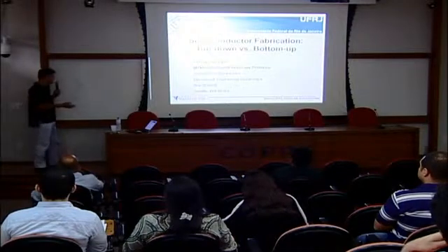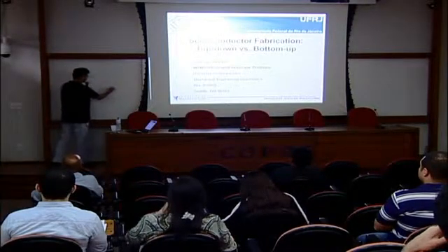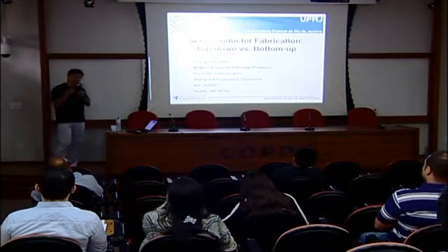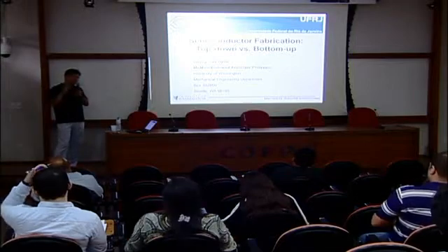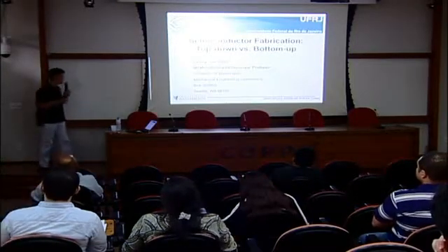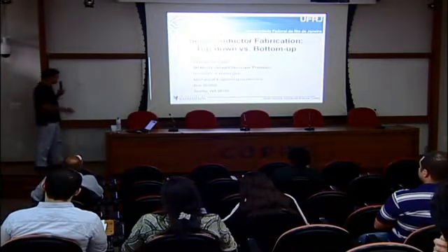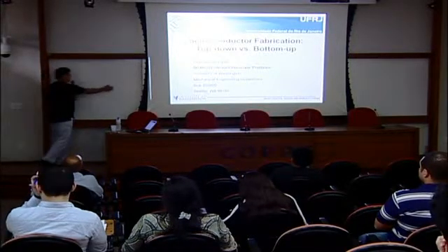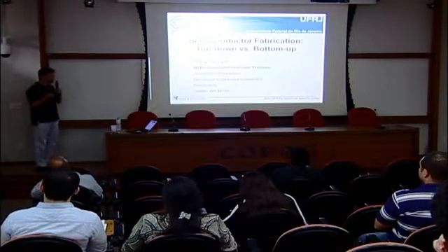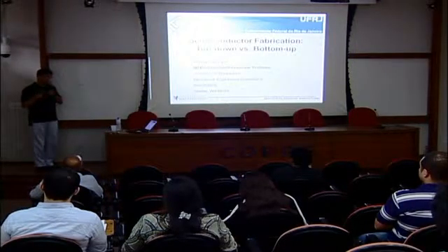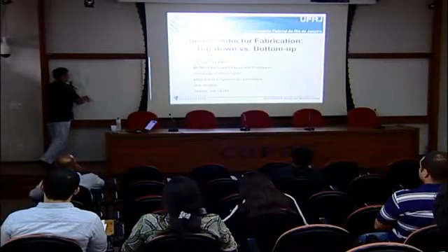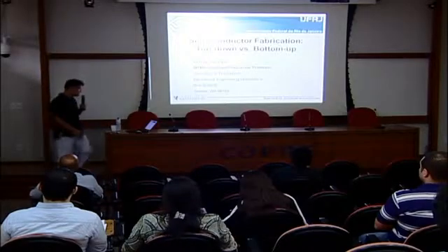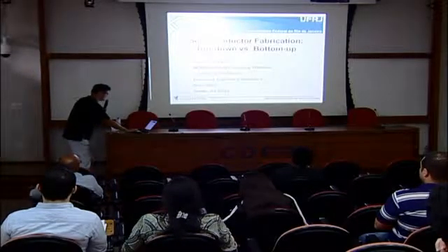For the bottom-up case, for instance nanotubes, the good thing is that a nanotube is not oxidized as readily as silicon. The oxidation depth of silicon is about 3 to 4 nanometer, but for nanotubes, technically we can remove all the oxygen on the surface. So this one is more futuristic, but it has a lot of problems in fabrication. We will discuss the manufacturing challenges out there.